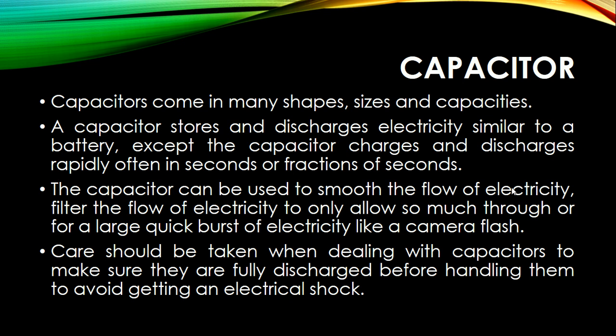Care should be taken when dealing with capacitors to make sure they are fully discharged before handling them to avoid getting an electrical shock. Actually, there is an electronics major, an instructor, who said that if you're familiar with cathode ray tube TVs, the fat TVs, as I've learned as a computer major, as long as the plug is not connected to the power outlet, it will have no charge at all. They say it is different with CRT televisions, because even though their plugs are not connected to the outlet, they still have charge because they have a very big capacitor, and it might harm you, it's not might, it will harm you if you are not very careful with those CRT TVs.